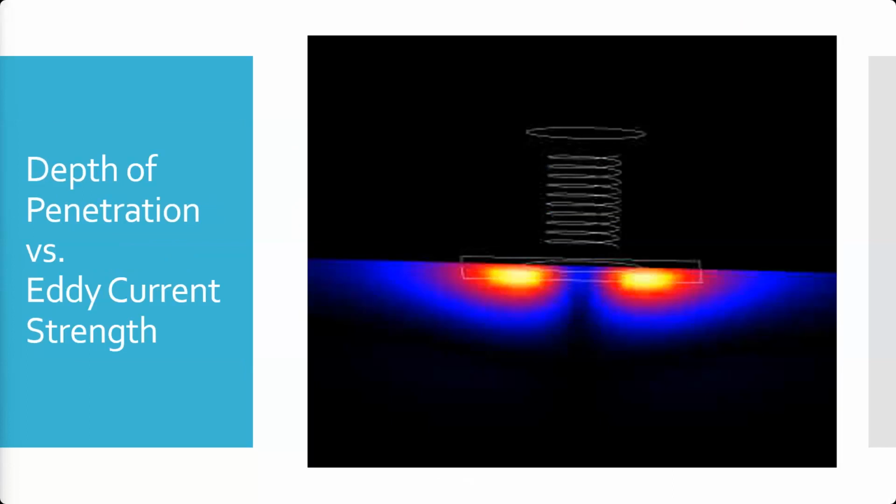Another example with a heat map. So this is taken with a magnetometer heat map. You can see the probe coil here, and it shows where the magnetic fields in this case are the strongest, which also means where the eddy currents forming are going to be the strongest. So with a circular coil like this, it actually is kind of a donut shape. And it's big enough you can see that separation. So there is a slight dead spot in the center, but again, it's donut shape. As you're moving that around, you're not going to be able to get to that center dead spot without going through one of those live areas that make up that donut.